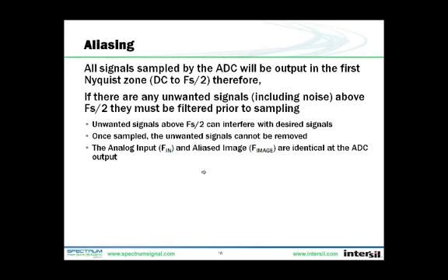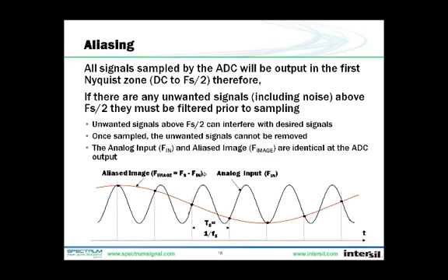It's also easier to visualize a low-frequency signal that has many sampling points. Now, as you can see in this example, two very different input signals, the black and red trace, both line up with the ADC's sampling points and will generate the exact same sampled output. There are an infinite number of higher frequency signals where the sampling points will line up correctly, and all of these signals will alias to the lowest frequency signal at the ADC's output, shown by this red trace.